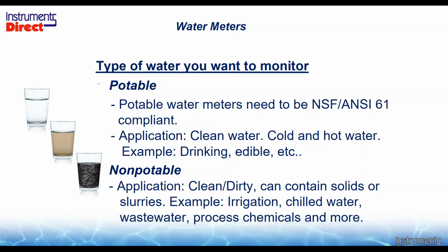So potable water has certain standards as far as the flow metering technology that you install to have the water run through. If you're going to drink the water, it needs to meet certain health requirements and certain industry standards. NSF Standard 61 is basically saying this flow meter technology is compliant with the health codes.